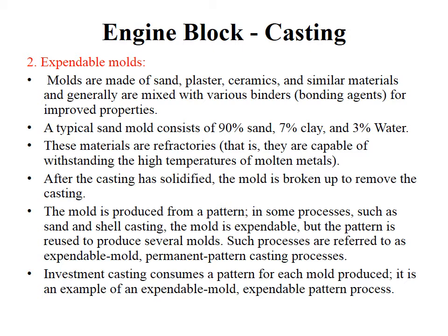Once the casting is solidified, the mold is broken up completely. So this is what expendable means: the mold is broken up and destroyed. That is why the name expendable. In some cases the pattern itself is expendable. In sand and shell casting, the mold is expendable, but the pattern can be reused for several molds, and those processes are known as expendable mold, permanent pattern casting processes.